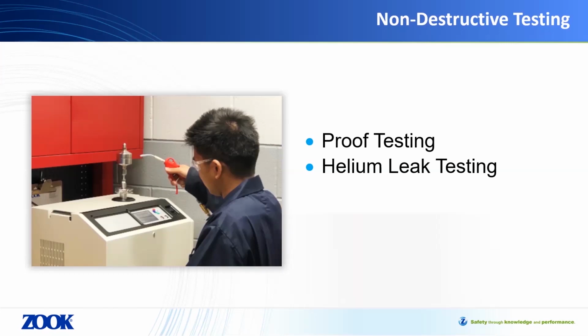In addition to ensuring the mechanical and leak tightness properties of a welded product, there is also a usual need for various weld inspections required by codes. If you are familiar with weld design, you will be aware of some of these processes, including liquid penetrant inspection, magnetic particle inspection, and visual inspection to ensure that the surface and visible finishes of welded joints are free from defects. X-ray and CT imaging may also be offered if your application requires validation below the surface of the material to further prove the quality of the welded joint.